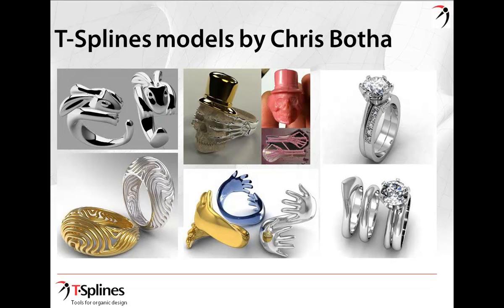Because I can just pull up extrude certain sections and then add in some edge loops to give myself a hard defined border. And stuff like that I would have had to use booleans before. What I now do is, like I was saying to Hamish, I have what I call T-collets. Inside my matrix I have a little folder with all my little collets, and because they still have symmetry applied to them, I can pull out any size stone, pull out a little T-collet, and just drag my arms out until it fits the stone.